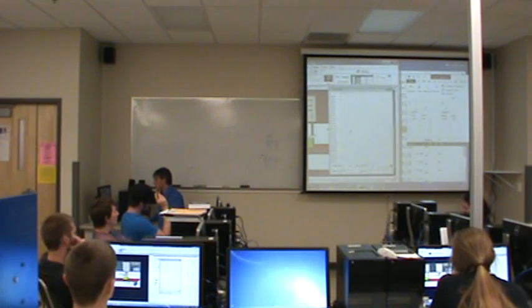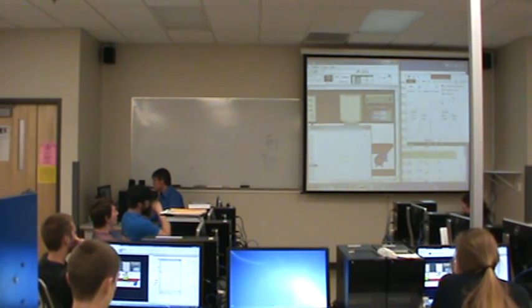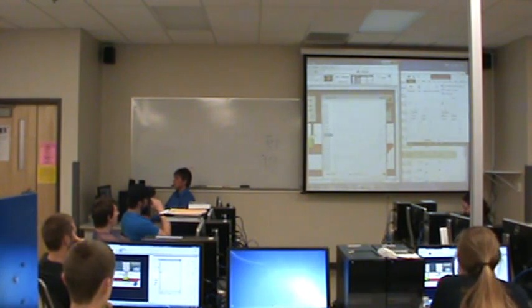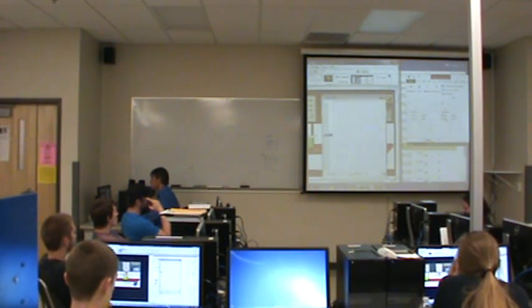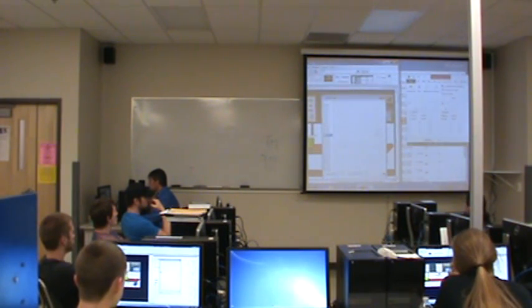Now let's set the outputs. The outputs start on address 11 because if you remember, well, I won't show it to you, but what I used in the sequence output instruction was actually address 10. I have to go one past. So let's see, output 0, output 1, I've got these backwards as well. That's fine, it doesn't really matter. But I'm dealing with bits 0 and bit 1.